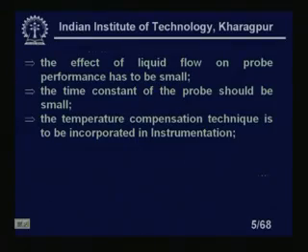Anyway, a temperature compensation technique has to be incorporated in the instrumentation, because as you know, if the temperature changes, many properties of the probe will change, since the electrolyte properties will change. So some sort of temperature compensation, or more precisely ambient temperature compensation, should be incorporated. That is a part of the instrumentation.